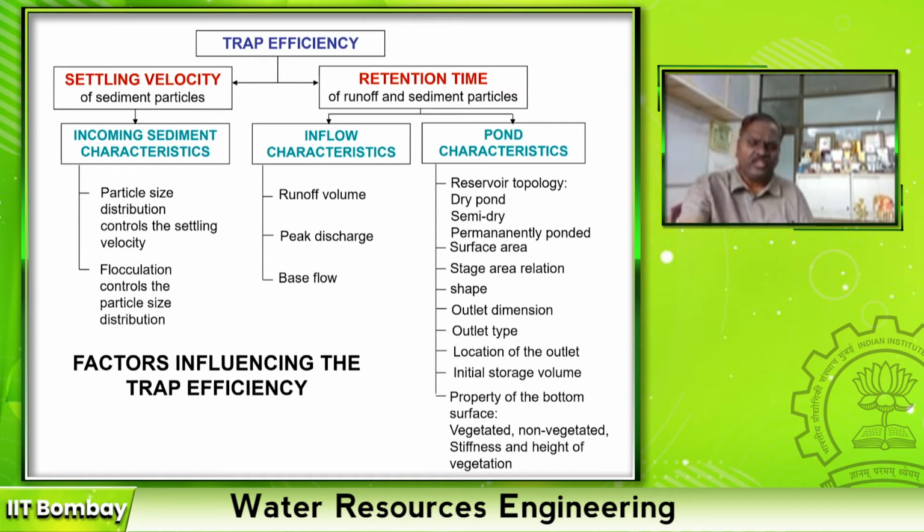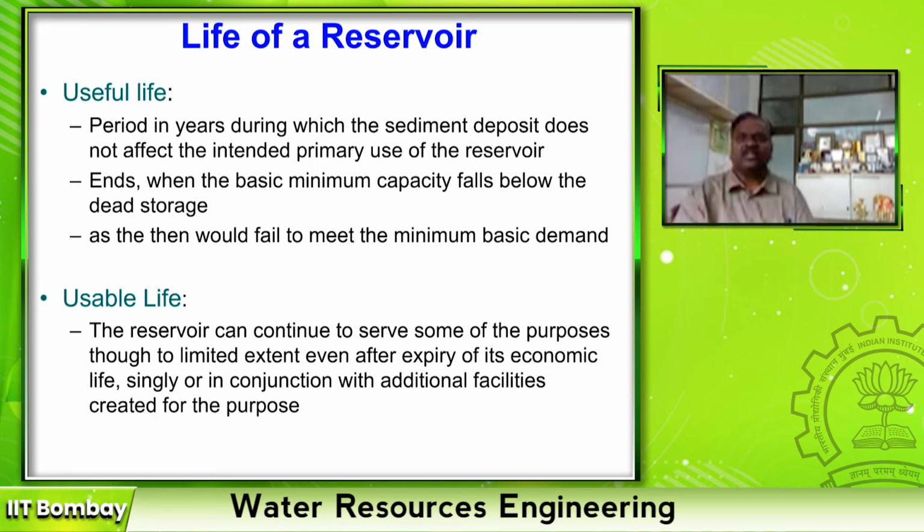So this trap efficiency estimation was the subject of study from the 1930s and 35s after the formation of large reservoirs. Why is it very useful? Because this trap efficiency is useful to estimate the life of the reservoir. It is not the structural life, but the hydrological life.